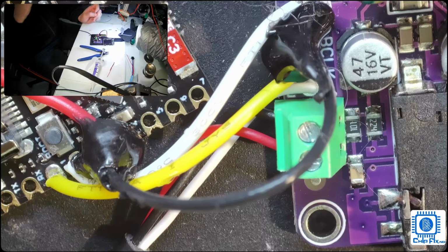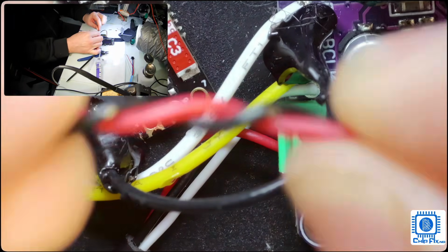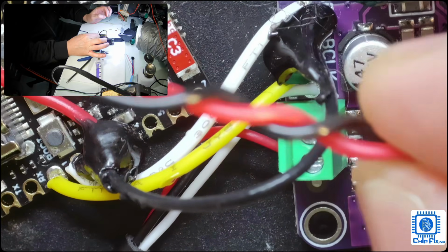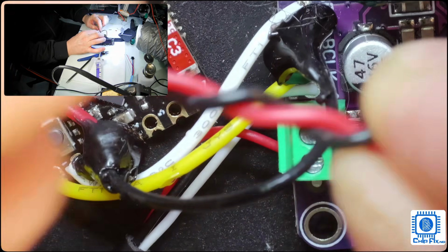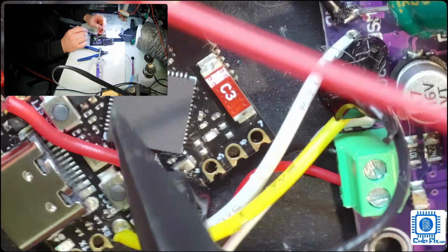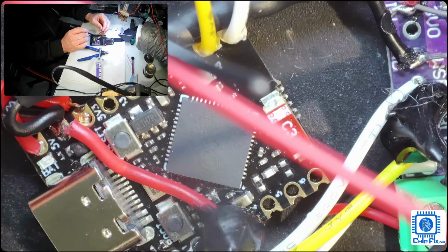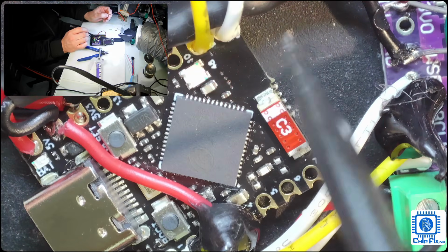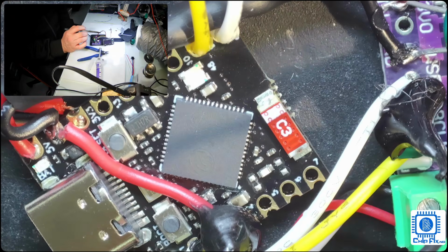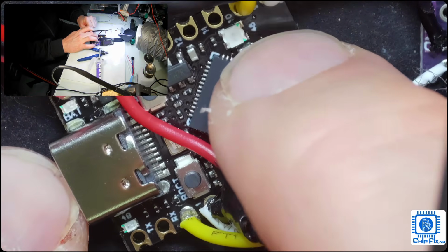To avoid that, there are a few things you can do. I have twisted the wires, and that should reduce the power circuitry from picking up EMF noise and Wi-Fi noise, and it's working very well. I made this earlier without anything, and you can hear it when it doesn't do anything. You can hear it in the speaker.